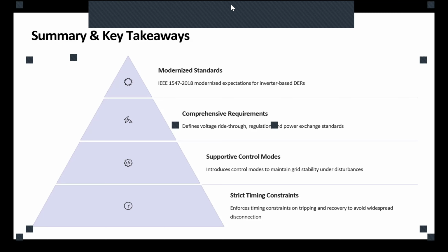All the fault ride-through that we talked about was during the fault. So a short circuit, for example, happens in the system, and until we fix that short circuit and get back to the normal situation, we have a fault period. Fault ride-through is for that part.